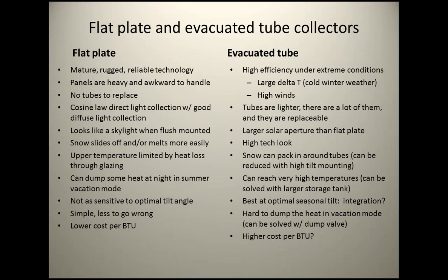If you had an off-grid place and wanted hot water in the wintertime, with propane as a backup, then you'd want to mount these with a high tilt angle. You've got to integrate that into the architecture. You may not have a high tilt angle in your roof, and your choice is making a high roof angle where you don't necessarily want one for architectural reasons, or putting up a rack, which is really very good. So I like the flat plate for that reason.